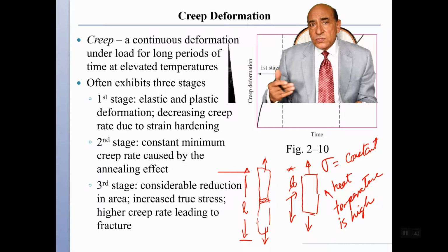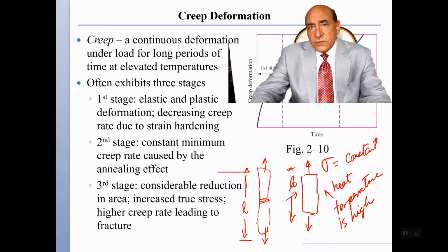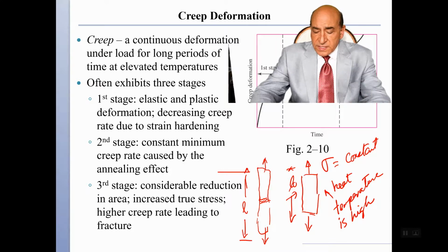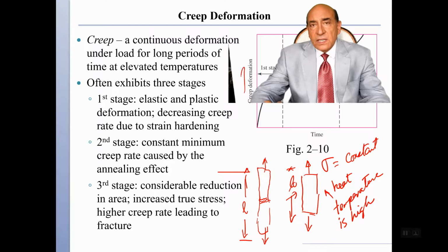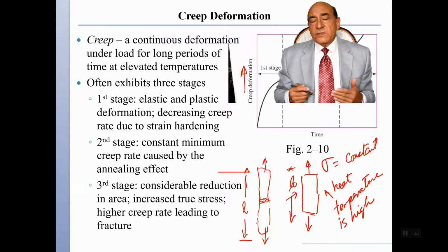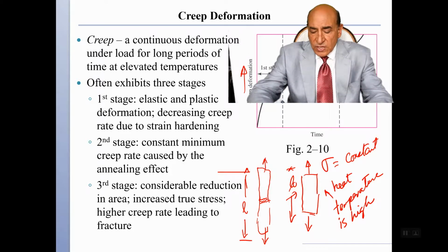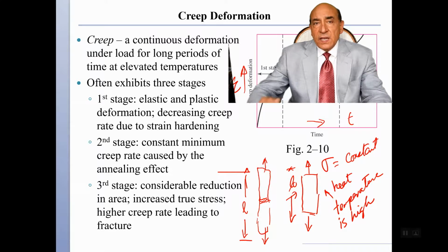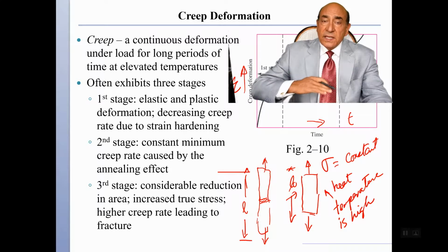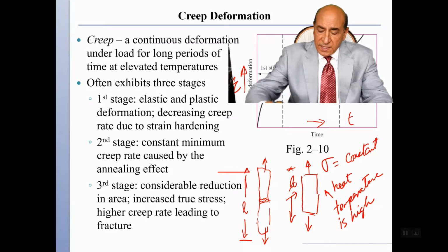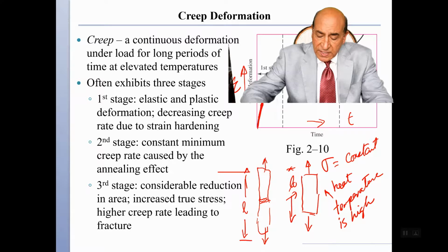The deformation goes into stages, and generally we can describe it with 3 stages. If we look at creep deformation on the vertical axis, measured by either the length of the sample, or most likely by the strain that we can determine. If it is a true strain, it will be the logarithm of the length divided by L0. So assume that this is epsilon on this side, and if we plot this as a function of time, the strain initially increases very rapidly. So we have an initial phase in which the strain increases very, very quickly.